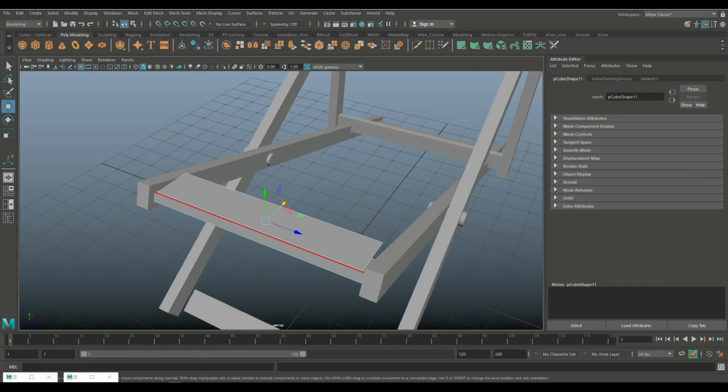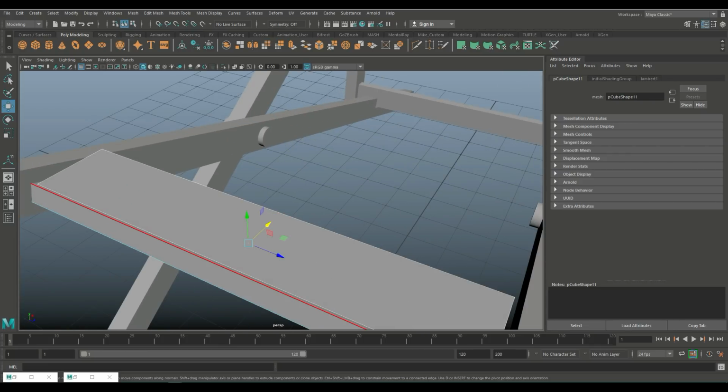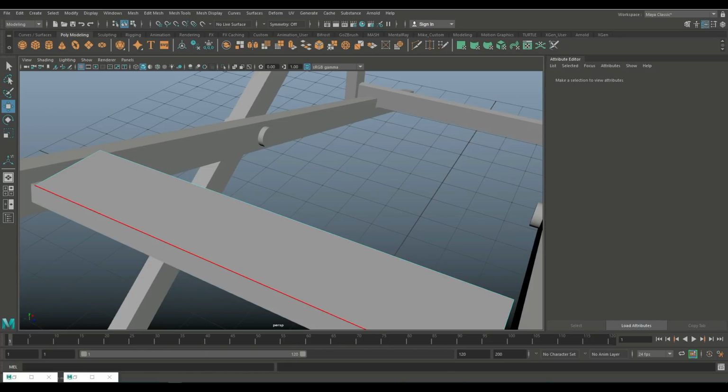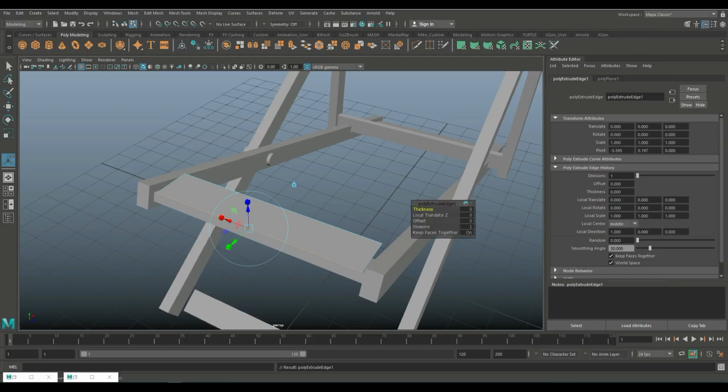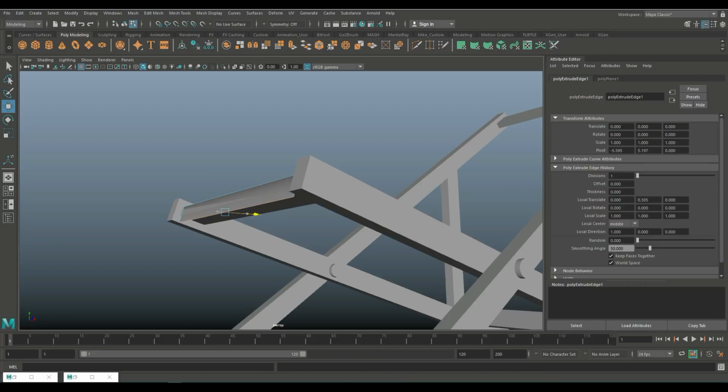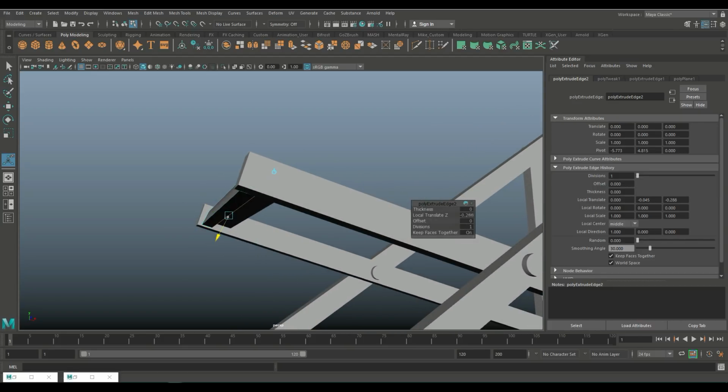So if you go in here to edge and take the edge of this guy, make sure we got the right one. Pull it out a bit further. This guy, and we hit Control E to extrude. We can pull out and push down. And push in. Hit G to repeat and push it like this. And maybe push up.